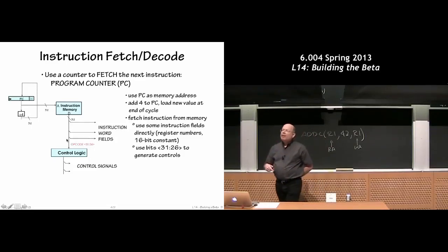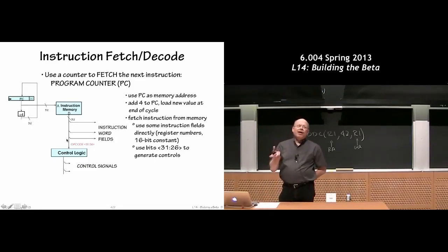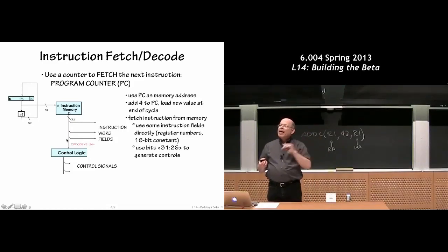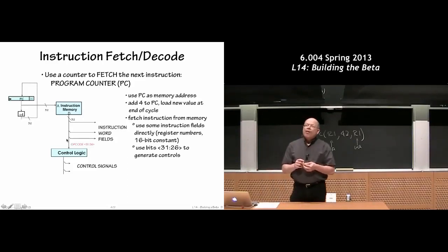Why is a PC a multiple of 4? So just to reprise our apologia about byte addressing. We use byte addressing. In other words, we think of each 8-bit quantity in memory as separately addressable, so each one has a unique address. Because we are building a memory system that only fetches 32-bit words, the load and store instructions always fetch a 32-bit quantity, so we will always be sending over an address that points to the low order of the 4 bytes we want to fetch from memory.